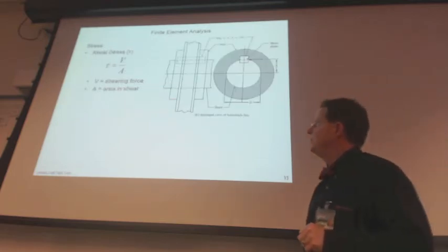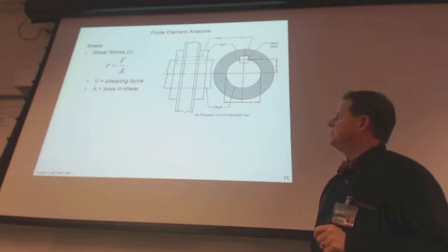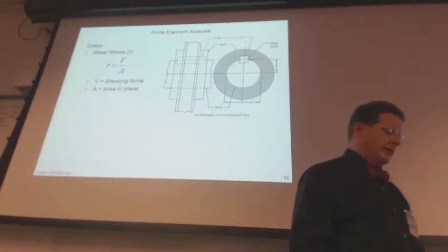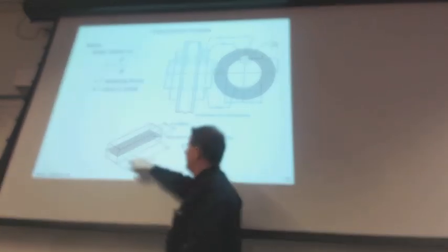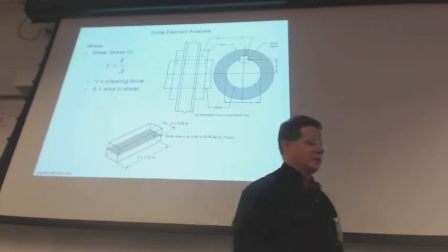Shear, just the concept of shear, the force over the area, and you have to make sure that you know what your, this would be direct shear as opposed to transverse shear, which we won't have to deal with. So this is your shear area for that keyway, because you have a force from the hub and a force from the shaft, and this is where your direct shear is going to happen.